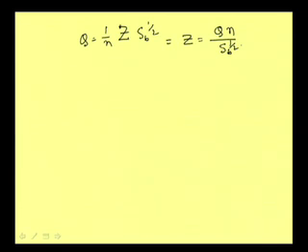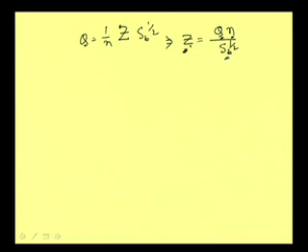Well, what it means is that section factor Z is a parameter which is related to the sectional dimension of the flow section, but we can get this indirectly: when discharge Q is known, Manning's roughness coefficient is known, and bed slope is known, then by this expression also we can find out the section factor Z. Well, now using this advantage, some graphs were plotted, and then those graphs were made non-dimensional.